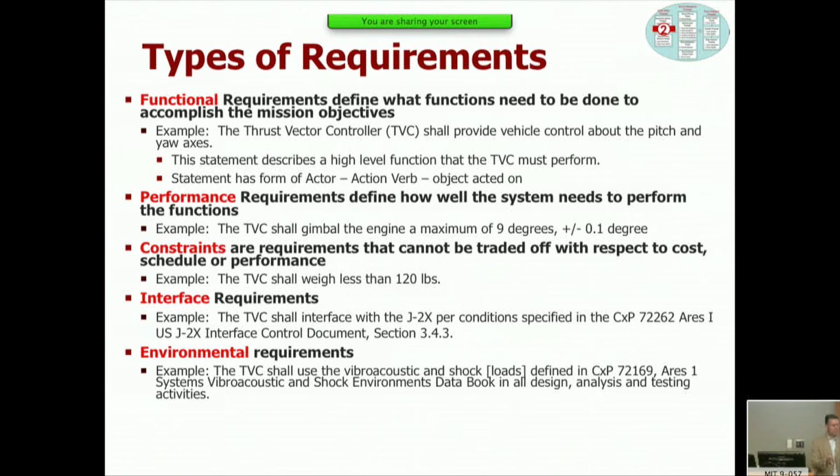And if you think about it, designing a sensor or anything to operate between 0 degrees Celsius and 30 degrees Celsius, or between minus 60 and plus 80, is a huge difference, right? You can write that down, but what it actually means to open up the range of environmental conditions has a big impact on the design, right?